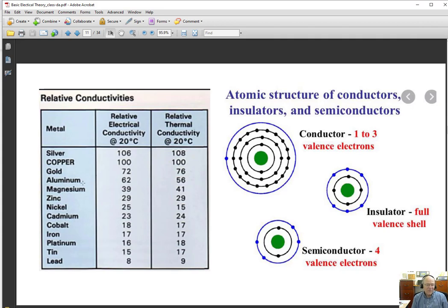It's just far, far, far less expensive to move electricity from a power plant to your house using aluminum wire than it is using copper wire. And as a result, it's worth it to use aluminum. Now, why don't we just use aluminum in your home, in the walls? Because of that problem of corrosion that we talked about earlier.